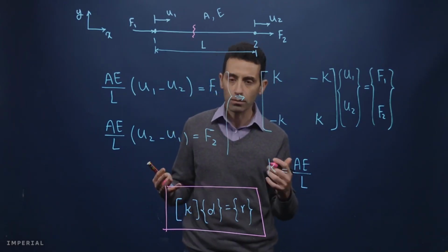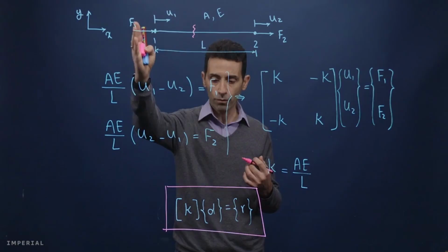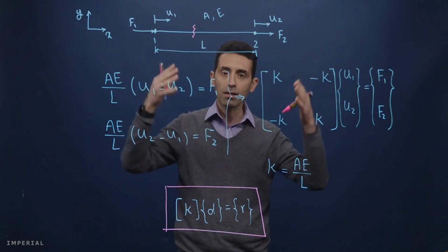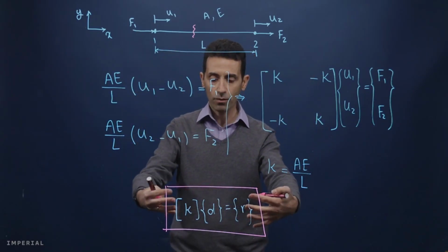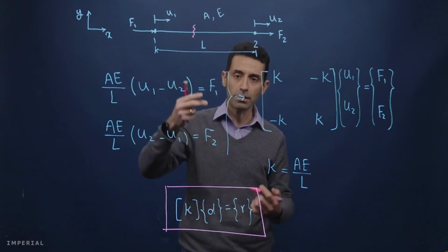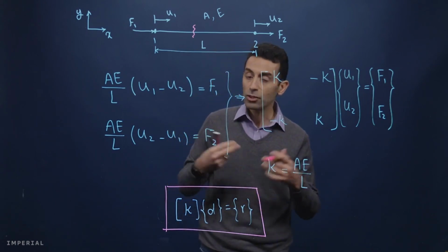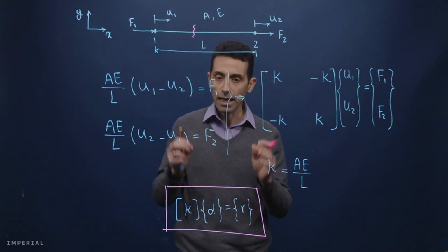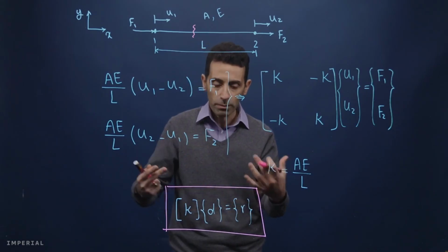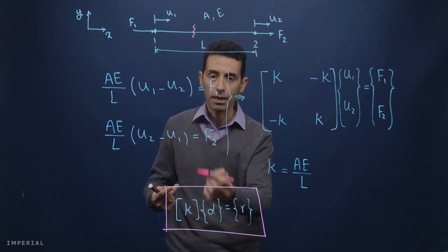So in the finite element method, whatever we do, we are trying to find a relationship between displacement and forces, and then always we do the calculations, but finally we summarize everything into a matrix format, very much like what you see here. So it doesn't matter if you are using a truss element, a beam element that we are introducing next, a solid element, shell element, etc. It doesn't really matter. At the end, everything will be consolidated into a simple equation like this. What will be different, of course, is what you will have in these vectors and in this matrix.